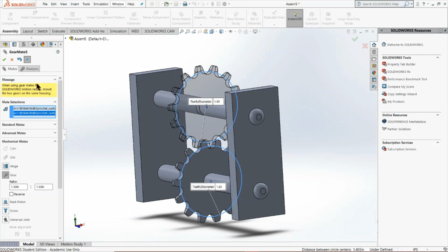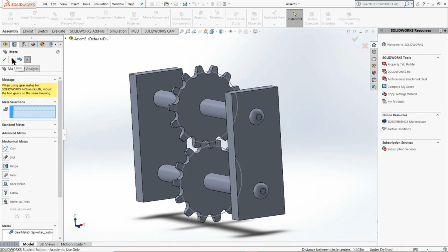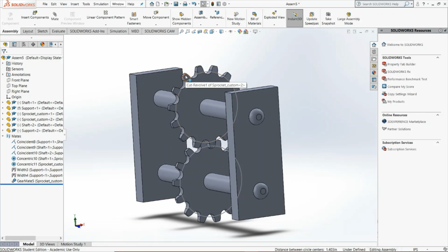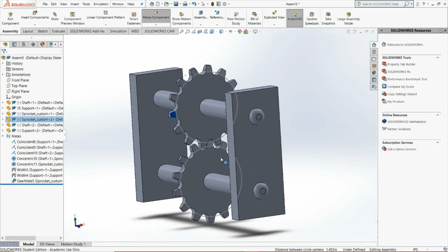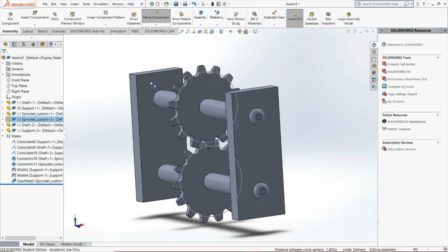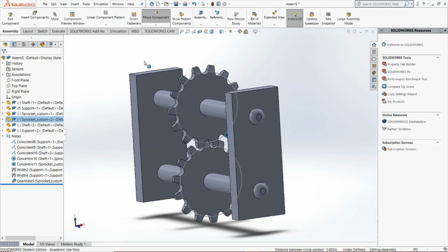So they'd move at different speeds of one another like an actual gear / sprocket system would. But if we press OK and close this, hold down the right click on, doesn't matter where, these two objects will move in tandem with one another. So that's very nice, especially if you're trying to do a motion study of any sorts.